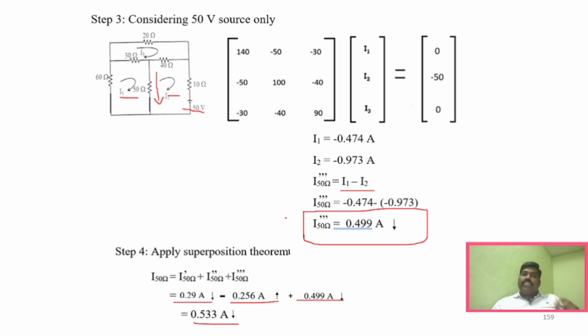So it is the same steps. If the circuit becomes complicated, you have to use mesh analysis. If it is a simple circuit, you can solve it using series and parallel resistor connections itself, right? So simplification of the circuit is very important, but you have to take one particular source at a time, simplify that particular circuit, and find the current across that particular element, right?